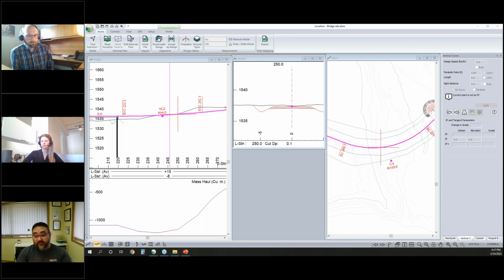Because there's a bit of a history here in BC of there being issues with that, certainly on the mining side, it's more of a focus. But yeah, it starts with just surface rock sampling, getting the testing done, and then generally some sort of a drill program if you are going to be excavating over 2 or 3 meters of depth. But that's where your specialist comes in. We certainly default to the geologist for that.